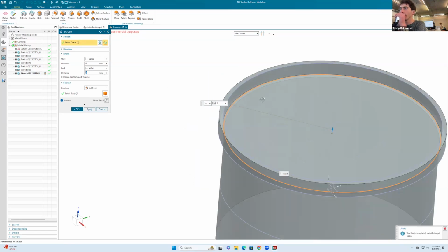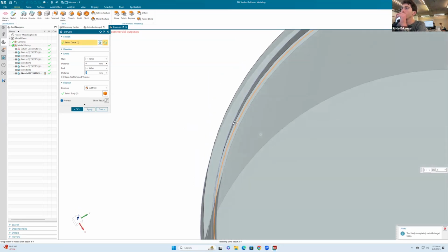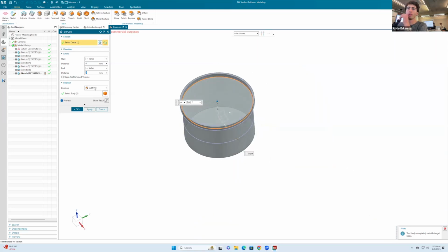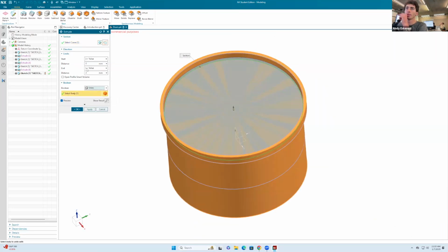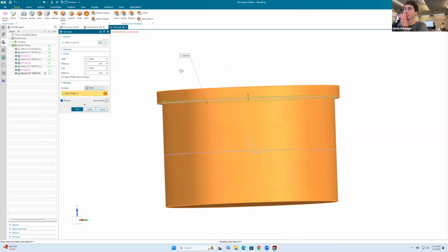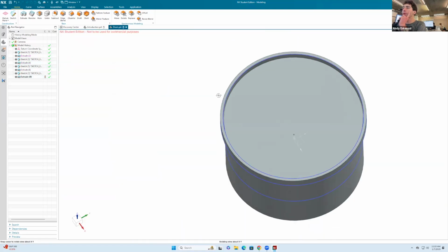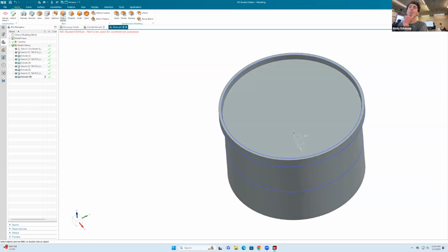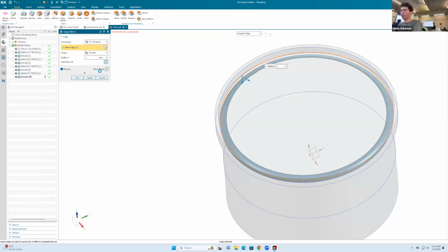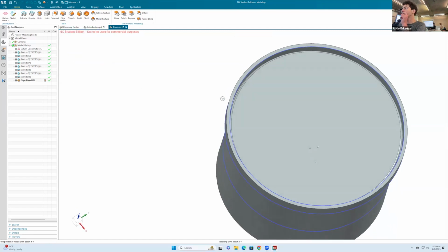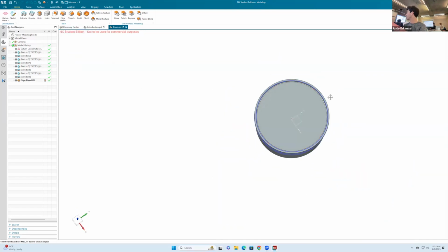By, let's say, 2 millimeters. I'll extrude upwards, so no, not subtract, I say unite. Let me make sure that I'm actually extruding in the right direction. Okay, I think it's okay. Good. So you see how there's the little gap. So then I can go to blend, like here to edge blend, and I'll click on that little line, and I'll make that just one. So now it kind of looks a little more realistic.